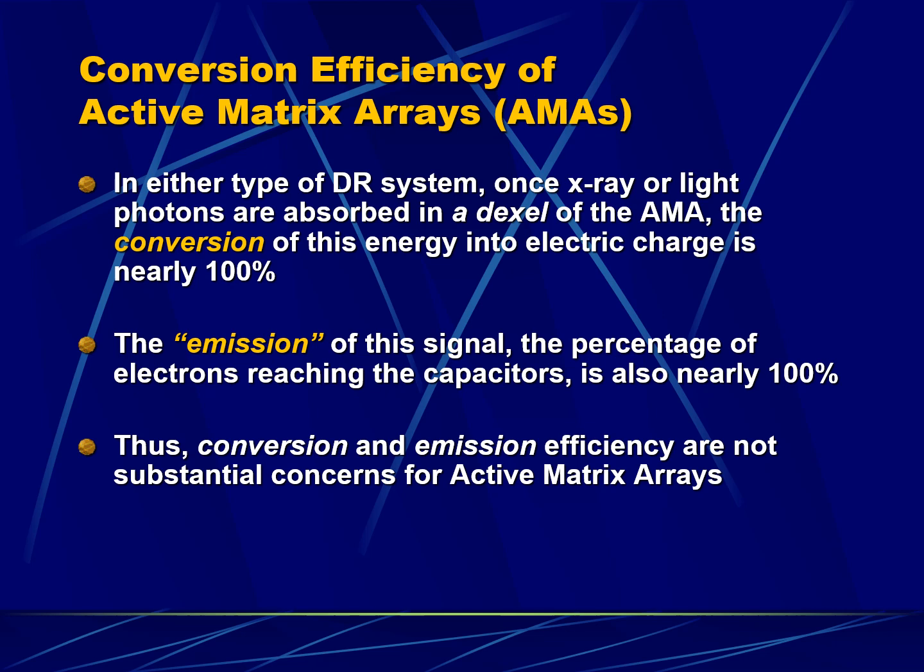In the same way, amorphous selenium, as it participates in the photoelectric effect, those electrons have to drift, right? And the positive ions have to drift, and one of those two has to be stored in the capacitor. If they don't drift because the steering force of that bias voltage, the top electrode, is too far away. Remember, what's the denominator for Coulomb's law? Oh yeah, distance. So if that bias electrode that is supposed to separate those ion pairs is too far away, well then those ion pairs self-neutralize. And I can walk you through that maybe next time if you need clarity on that.